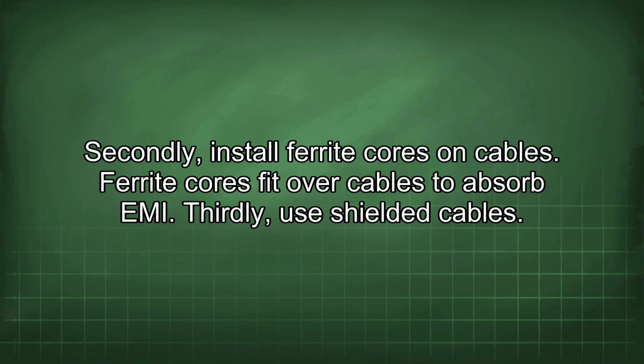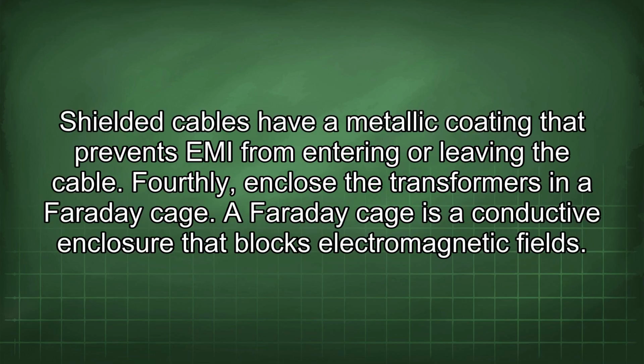Thirdly, use shielded cables. Shielded cables have a metallic coating that prevents EMI from entering or leaving the cable. Fourthly, enclose the transformers in a Faraday cage. A Faraday cage is a conductive enclosure that blocks electromagnetic fields.